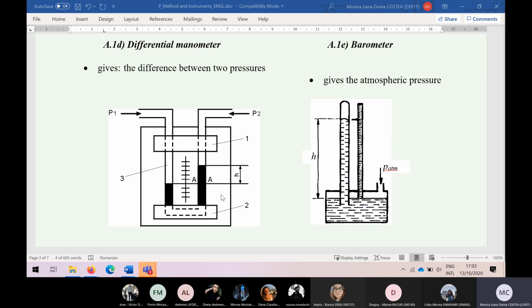We mentioned that the instruments generally give relative pressure, but not here when it's a question about a difference, because the difference will make the atmospheric pressure disappear, and it is not worth adding it. You do not know whether to put a plus or a minus between two terms, okay? So be aware that for differential manometers, the information is directly absolute pressure.